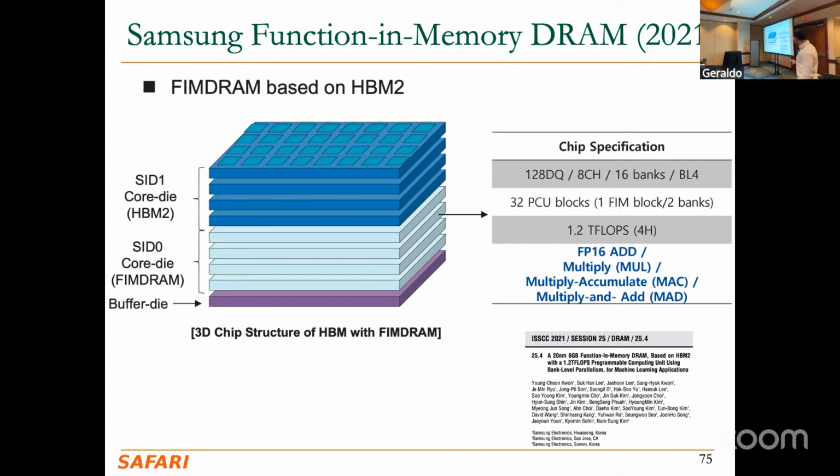In their initial realization, they take the HBM chip, and this is a little bit different from what I mentioned from the 3D stack memory so far. Here they are not using the logic layer to add computation. What they are going to use is basically some MAC units. We have X amount of DRAM layers in the DRAM chip, right? So they take some of those layers out, and then they repurpose those layers to have computation. So instead of having 8 layers that are pure DRAM, they basically have 4 layers that are pure DRAM, and then 4 other layers, which are DRAM plus some computation.